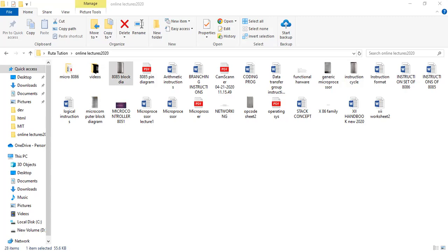Control signals are bidirectional. In serial input output, the SID and SOD pins take data in serially as well as output it. Therefore, this is bidirectional. Interrupt control: we saw these are 5 hardware interrupts: TRAP, RST 7.5, RST 6.5, RST 5.5, INTR. And there is one interrupt acknowledge signal. That signal goes out from the microprocessor to the external devices once the interrupt is acknowledged. Therefore, you have the bidirectional arrow here. Okay. So 1, 2, 3, 4 blocks are over.